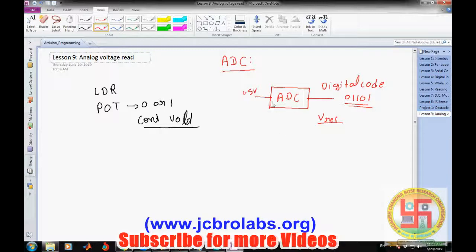We will not go into more detail of it, into the deep dive. We will cover the upper layer of this ADC. As we know, a continuous voltage has an infinite number of possibilities, right? So while converting to a digital code, we take only certain values of it. Let's take an example. Suppose we have a 3-bit ADC. A 3-bit ADC means it can give output from 000 to 111 in this range, right? Because a 3-bit ADC can give only these 3 bits of code.